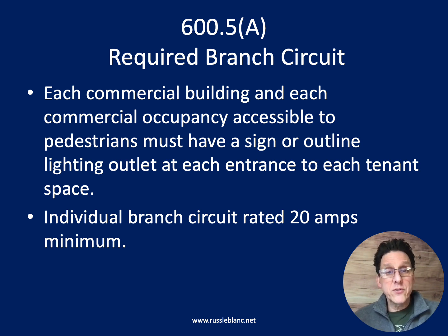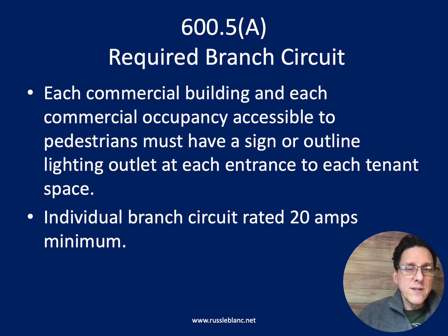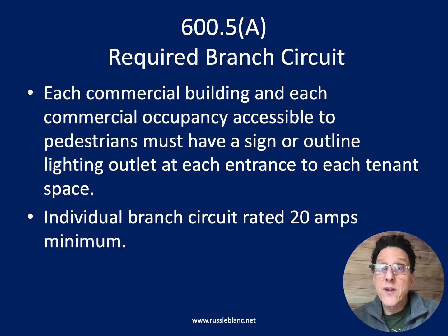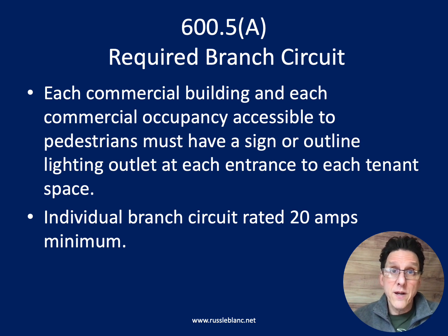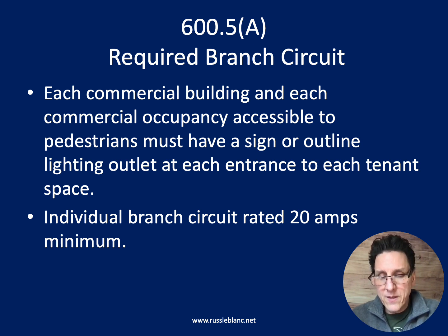As far as voltage goes, I guess that's your choice, right? The installer's choice. 600.5(A) doesn't tell us 120 volts or 240 volts or 277 or 480, whatever you want it to be, I suppose. Maybe someday we'll get that information, but right now the code does not say which voltage is required there, but it does say 20 amps minimum.